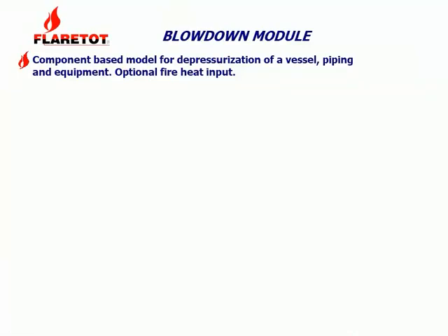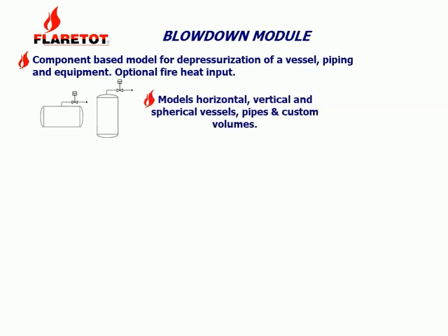This module calculates the time-dependent depressurization of a system, using component-based physical properties. The depressurization can be modeled from normal operating or during fire conditions. For fire cases, the extent of fire exposure on the vessel can be specified. Horizontal, vertical, or spherical vessel types are all allowed. Piping and equipment connected to the vessel can be included.